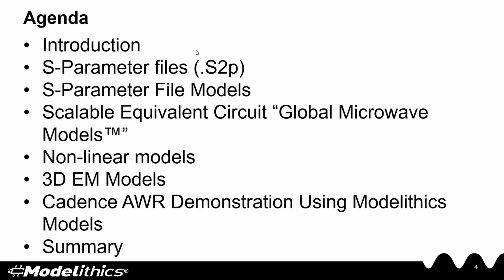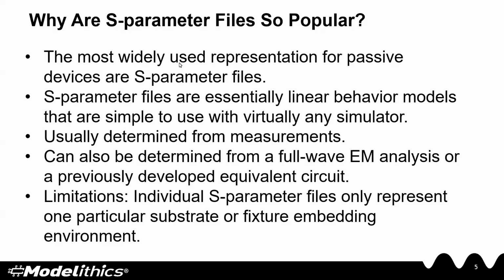So let's proceed. So let's talk about S-parameter data files. These are a widely used representation for passive components in the RF microwave industry. These are essentially linear behavior models that are easy to use with any simulator. And these are determined from measurements that the manufacturer performed.